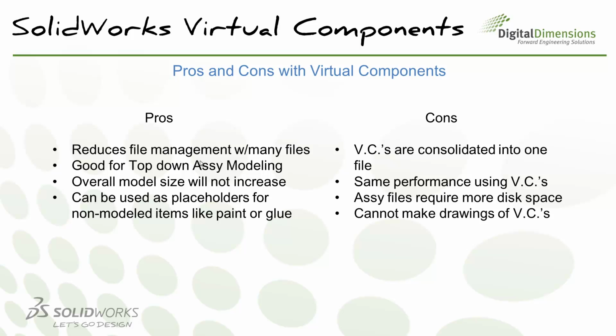Some of the cons with working with virtual components are the fact that virtual components are all consolidated into one file. So the phrase, don't put all your eggs in one basket, applies with virtual components. If you have a situation where that particular assembly file becomes corrupted, something has happened to it, you lose it, now you've lost all of that work for all of those virtual components because they're all embedded within the one file.